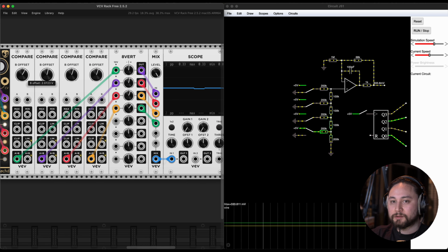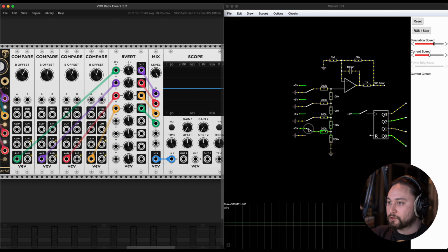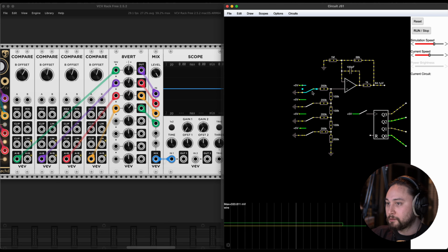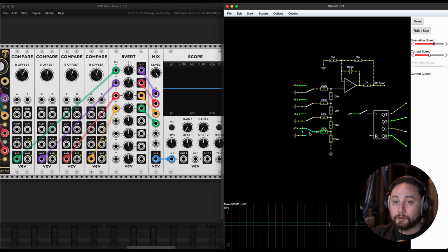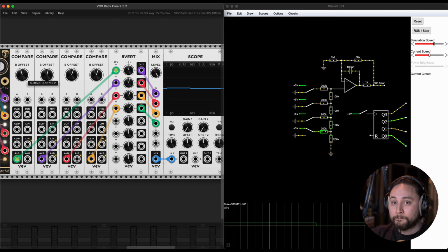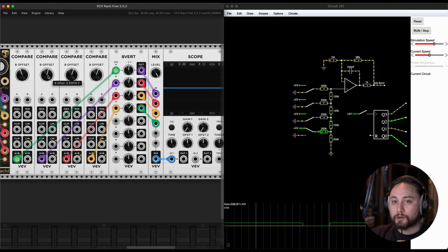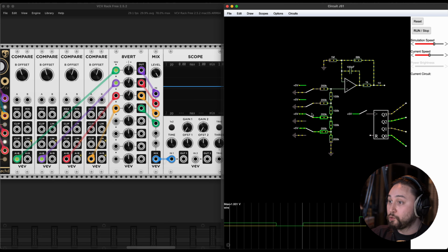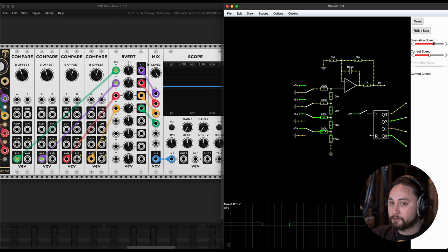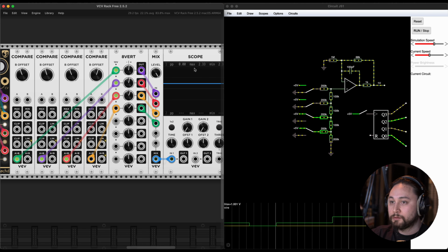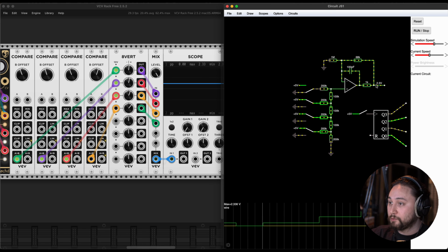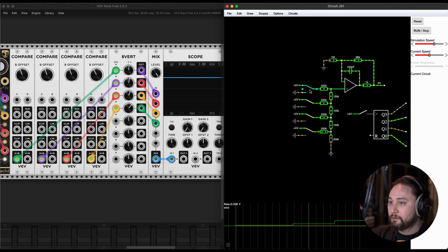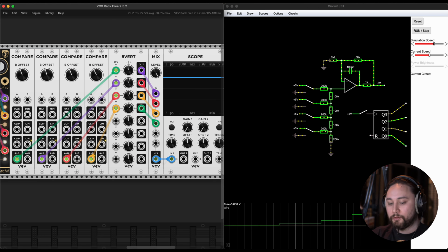Okay, offset. Let's take this up. So we're at zeros across the board. In this case, yeah, some microvolts there. Let's add our least significant bit. 0.33. That's working. Let's just add in our next one. So that's the 2 least significant bits. That hits 1 volt. Let's go here. 2.33. And the last one, 5 volts.